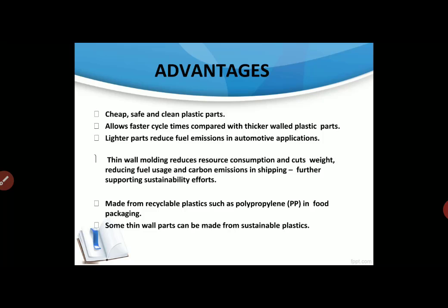Now we can see what the advantages of this thin walled injection molding technique are. Cheap, safe, and clean plastic products can be obtained, and it allows faster cycle time. The lighter parts reduce fuel emission in automotive applications, and thin walled molding reduces resource consumption, weight, fuel usage and carbon emission.